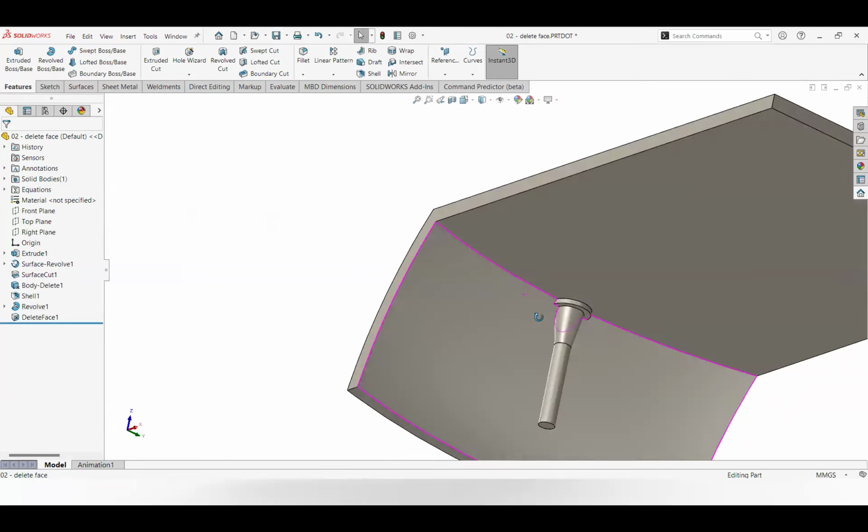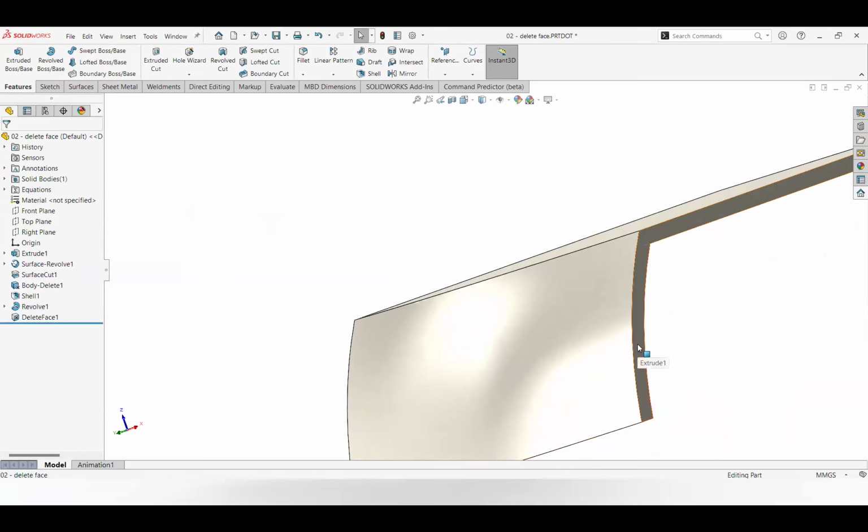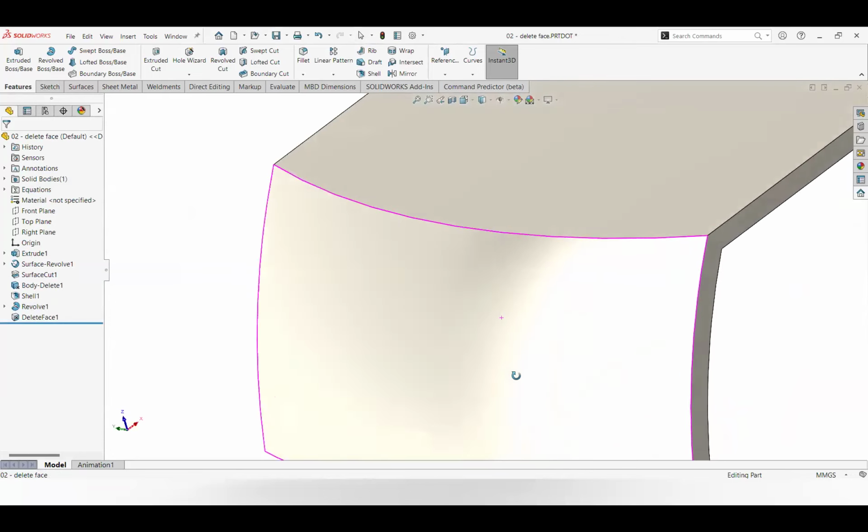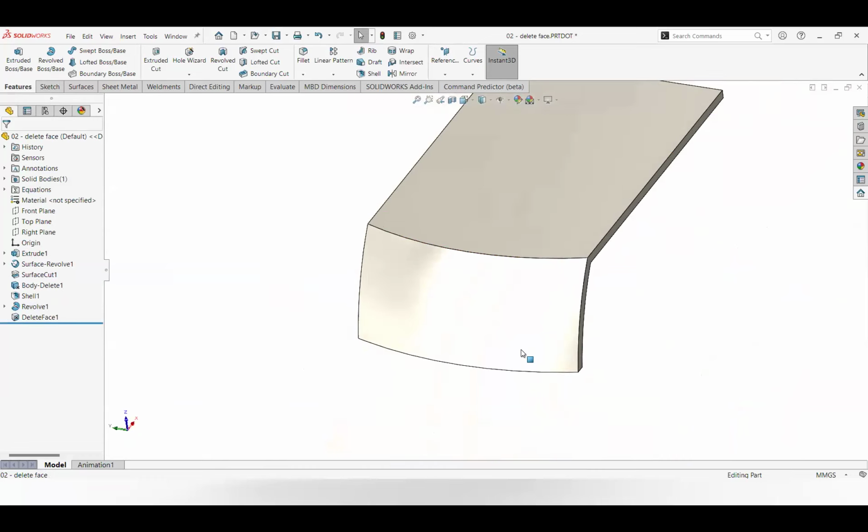And when I get to the example of the SolidWorks Bondo tool, it's really just the delete face tool, but with a little bit different option. So that can be really handy if you've made something inside and it's sticking out the outside. Fine, just use the delete face on the outside. Have any of you done that before already? Was that just an obvious one? Maybe.